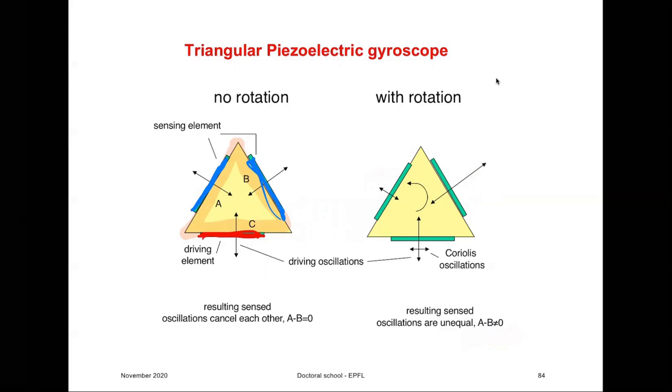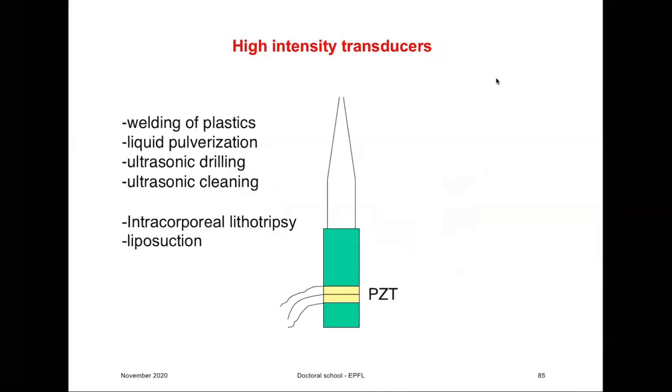And I think they had a Toyota car which was driving, navigating only by this piezoelectric gyroscope, and was able to make a circular road of about 300 kilometers and come back, navigating only by this, to a very close position to where it started from. Piezoelectric gyroscopes are used in helicopters, for example, where it is very important to know position, orientation with respect to the ground and so on. So a lot of that is for military, but also for civilian applications, consumer applications.